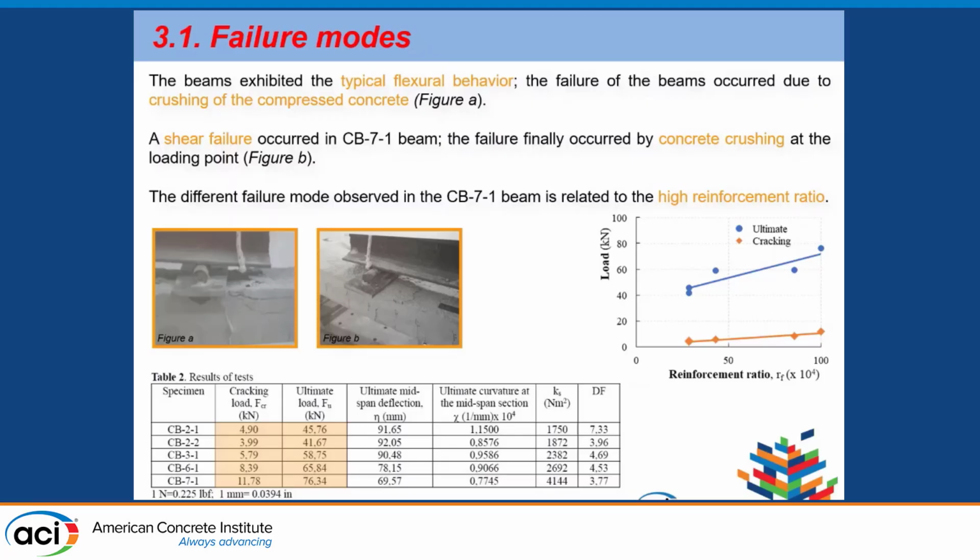And then from this plot we could already draw some conclusions. For instance, with increasing reinforcement ratio, there seems to be an overall increasing trend of the ultimate load, whereas this effect is more limited in what concerns the cracking load.